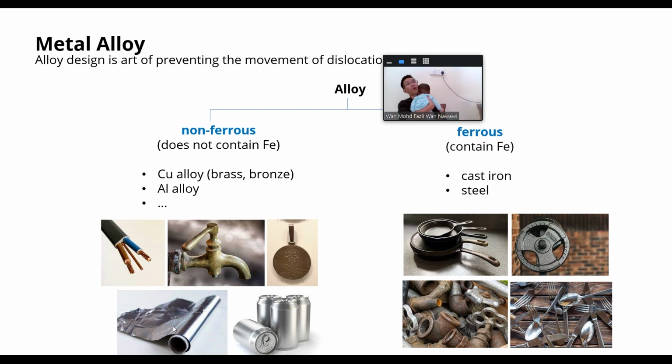So you can see not all aluminium alloys are the same, because here they don't add anything. Of course there are some impurities from the extraction, which is why we don't call it pure aluminium, but it is at least 99% aluminium. Here they add manganese to make it more ductile and stronger in some way. An example is aluminium 3004, which is made for the body of the aluminium can.